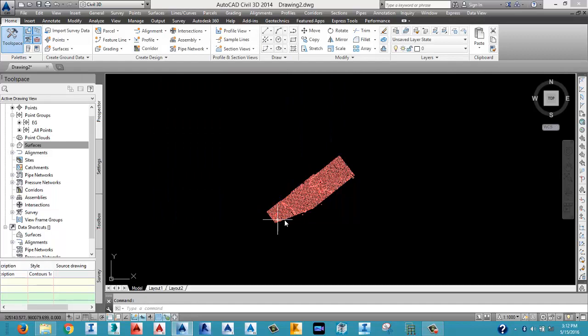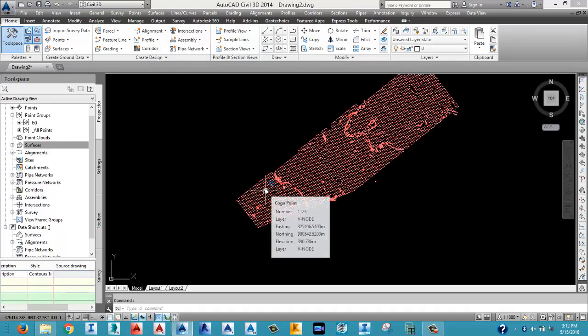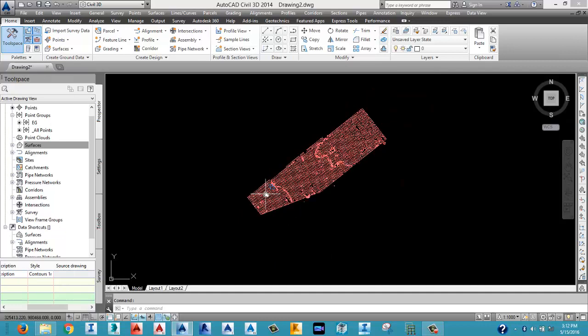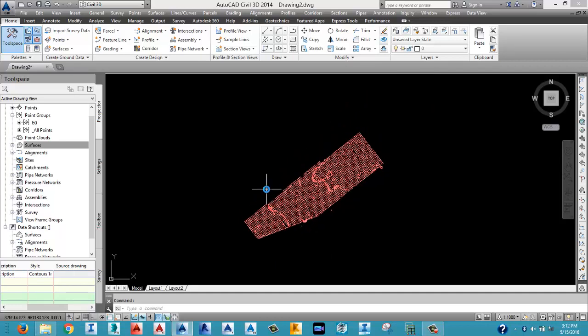Basically, all these settings are what you can create on your own. All these 1:5, 1:10, 1:20. In the long run, once you get used to the software, you can create the contour spacing at intervals you like. I might have my intervals to be 0.5 by 1 meter, 0.2 by 1 meter, depending on how I want my contour interval to run.